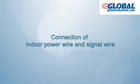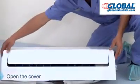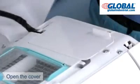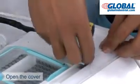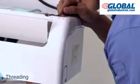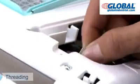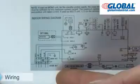Connection of indoor power wire and signal wire. Open the indoor unit panel. Loosen the screw used for fixing the cover of the electric control box and remove the cover. Put the signal wire and power wire through the wire outlet from the back. Connect the wires referring to the wire diagram.